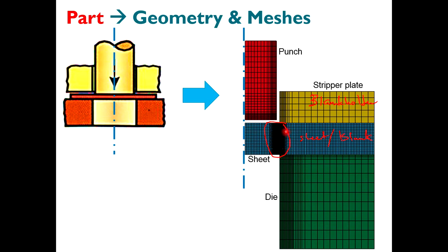because since this area is the cutting area, and the punch making contact with the cutting area is around this area, that's why I make it small mesh around here only. Okay, so the rest you can leave as big as possible. That's not going to affect the accuracy. Okay, but please bear in mind, the smaller the mesh, the higher the computation time. So you need to have some suitable number of it.